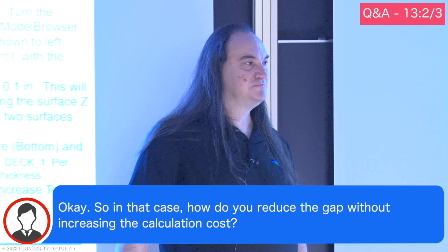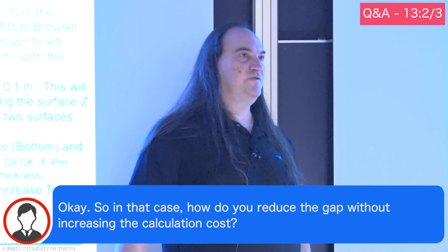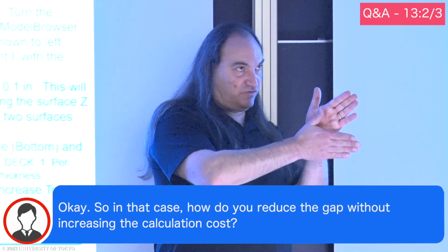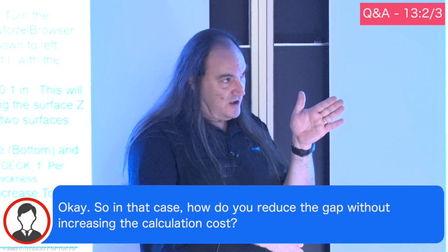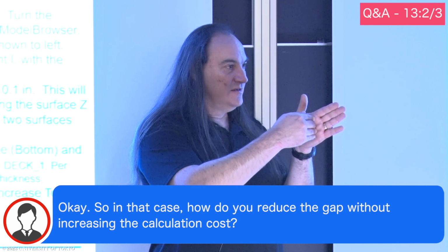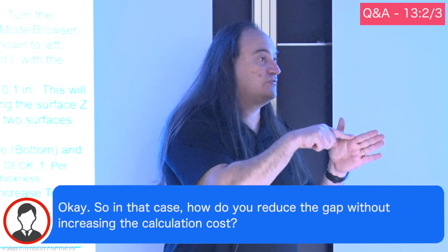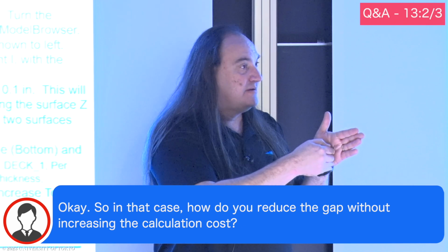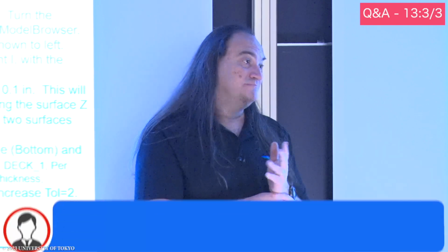Correct. So what you could do is, if you had a perfect surface as a curvature, and then you had the faceted surface, you could put a small ring just behind it that was very, very narrow and make that a blocker surface so that now no rays can get through there. So now you've closed that gap with a blocker surface. That would be a way to do it.